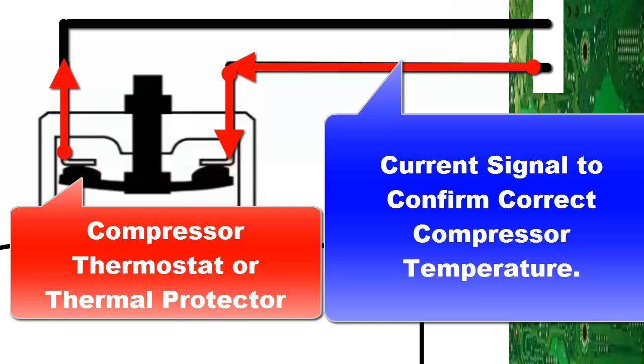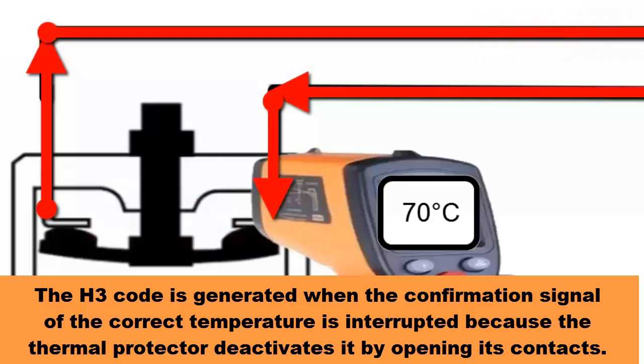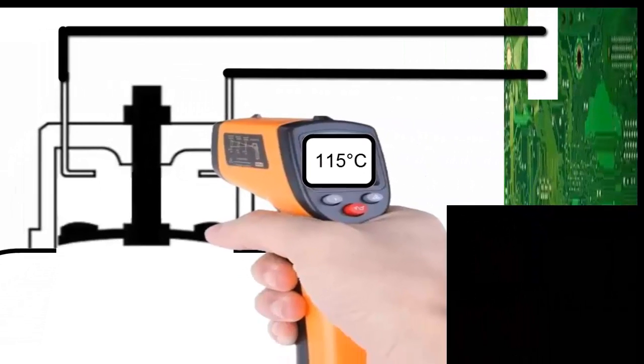This video focuses on the H3 error that appears on the screens of mini-split air conditioners from many manufacturers. Let's start by saying that the H3 code indicates a problem related to the compressor overload protection, detected when the compressor temperature generally exceeds 115 degrees Celsius.